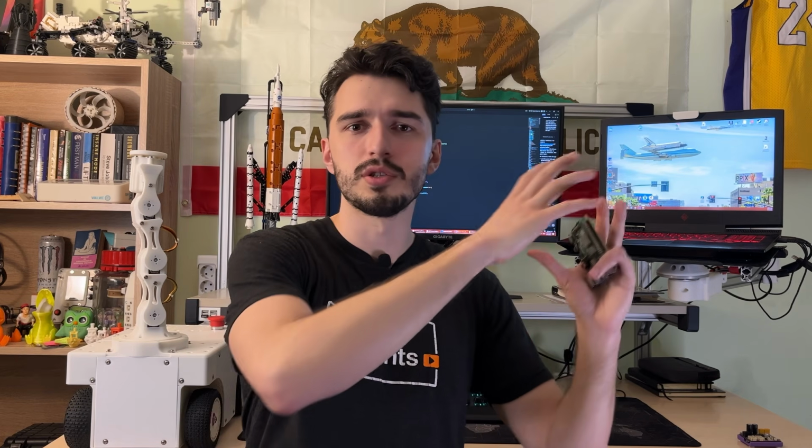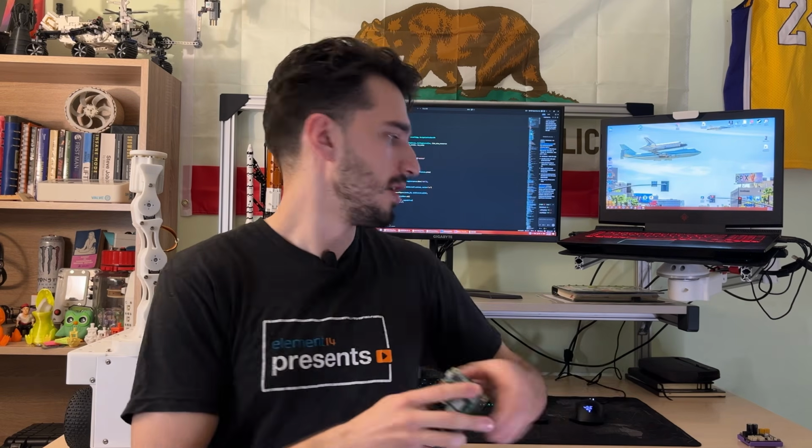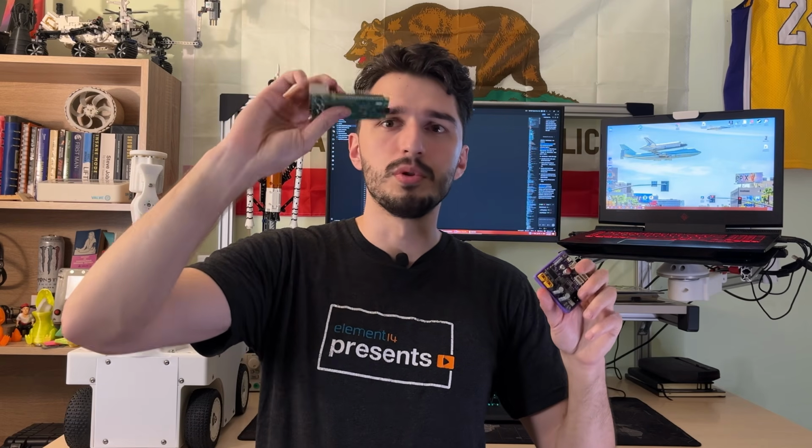Each of those nodes, imagine like a single Python script, for example. It can communicate between nodes using topics, using services, and other things that you will see now. And the idea with this is, for example, if we have a computer that has Robot Operating System on it and a microcontroller, you would have one node that just does communication with this, and then you would develop different control strategies, for example, and you would never have to repeat the code that just communicates. You would know always it works.